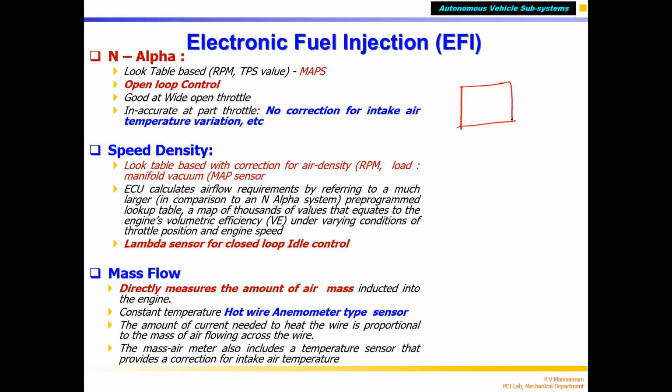That's why inside your ECU, you will not have one table. You may have 20, 30, 40 tables, correct? So this is the 30-degree table, correct? At 30 degrees, this is throttle percentage, 20 something, it goes on to 10%, and RPM, 2000 RPM. I am talking about a single cylinder, 3000, 4000. I go to say 6000 or 8000 RPM, the table extends. I made it for what? For 30-degree temperature.